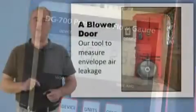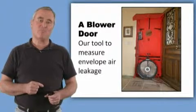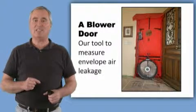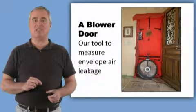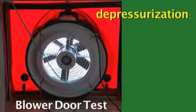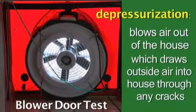So we always use a standard test pressure of 50 pascals. A pascal is a metric measurement of pressure and is equal to 0.2 of an inch of water column. We depressurize our house with the blower door fan to 50 pascals and measure the leakage at that pressure. At that pressure, the amount of leakage we measure is typically about 20 times the amount of average or typical leakage that would occur in the house.